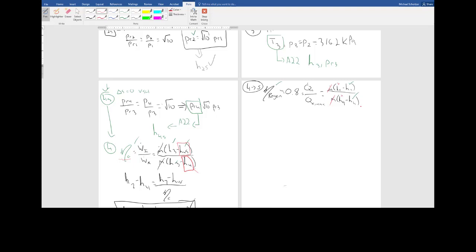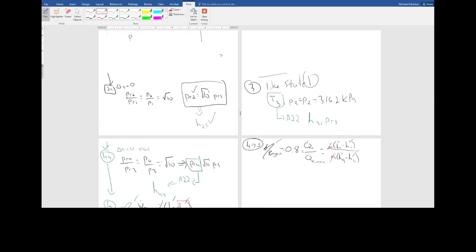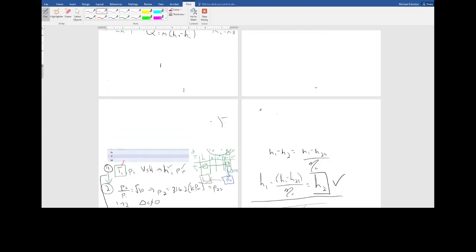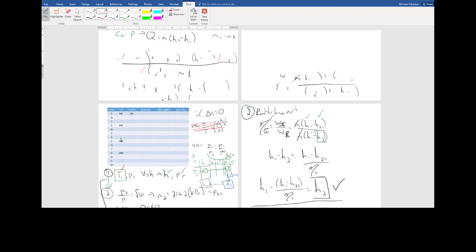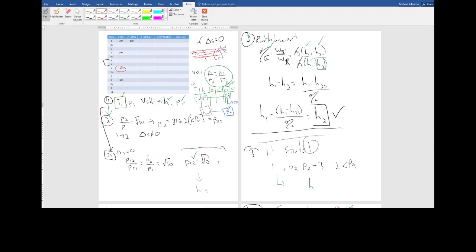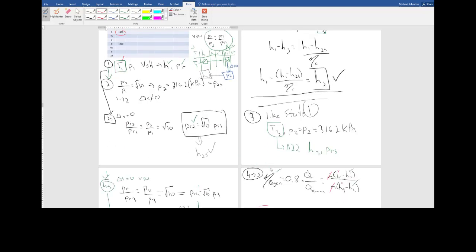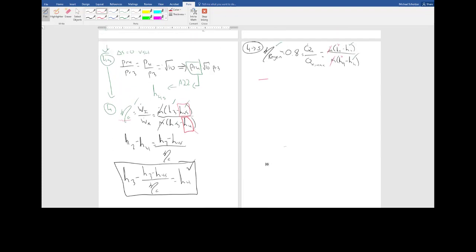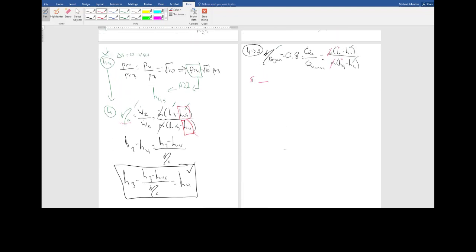So I'm going to skip it, right? And the nice thing about these problems is that if you get to a point like this, look for the next place where you have a given temperature, right? So here at state 6, they tell me the temperature at state 6. Right? So it's nice that it's the next one too, because that suggests that this is not a bad place to start skipping. Right? So now I'm going to skip and come back, but for now I'm going to move to state 6.